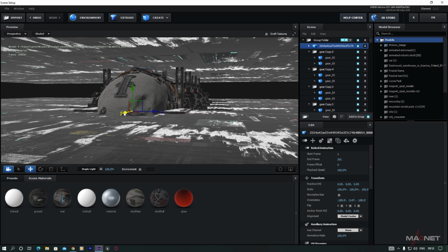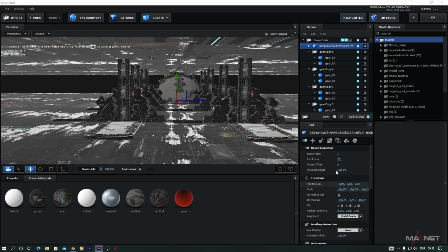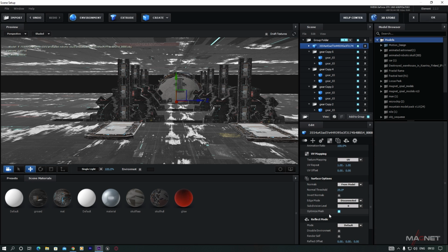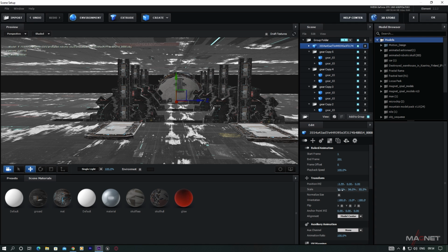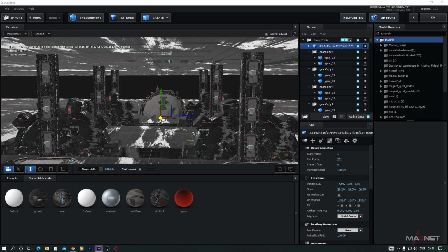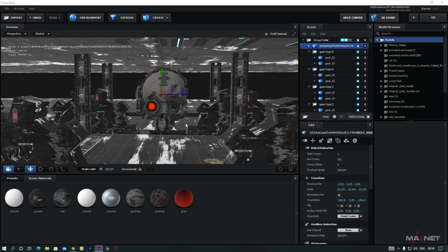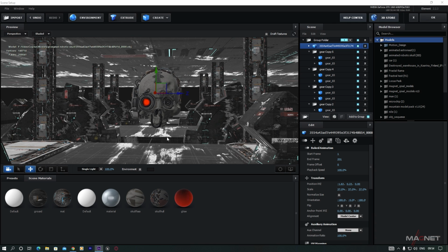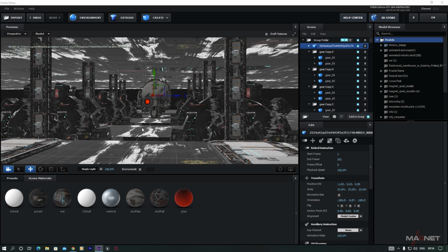And now we're going to reposition this skull model into the very back side here. Also, select this skull model, go down here, and make sure that you check this optimize mesh switch. Okay, and we also decrease the scale of this skull model, so we decrease this size and place it here. Decrease it a little bit more. Okay, just fit it in here and place it here just like this. So here is our skull model.